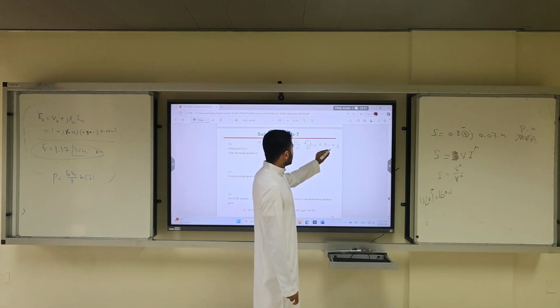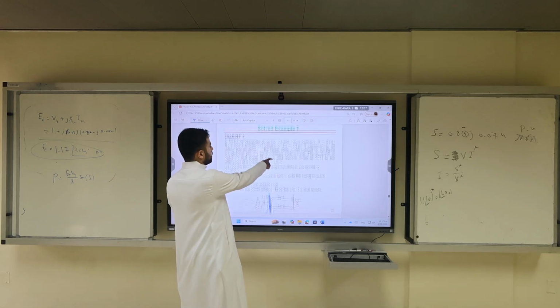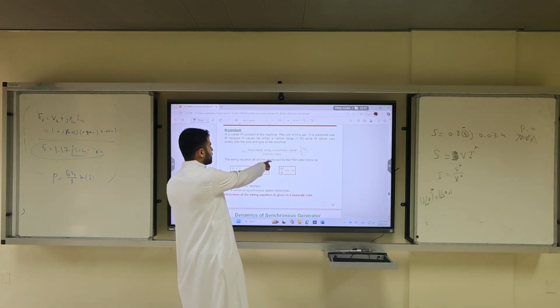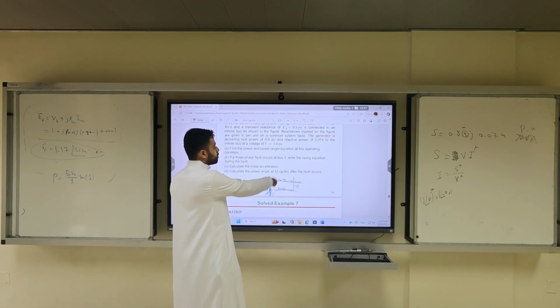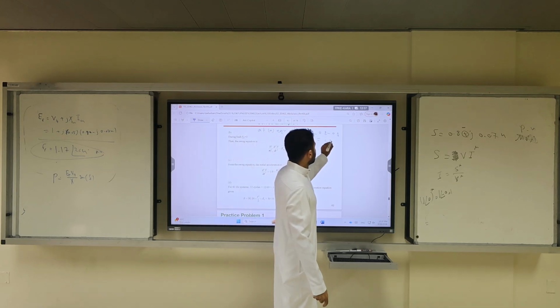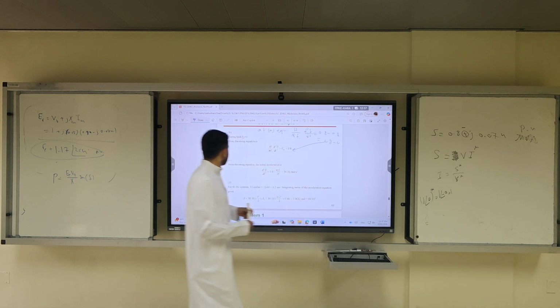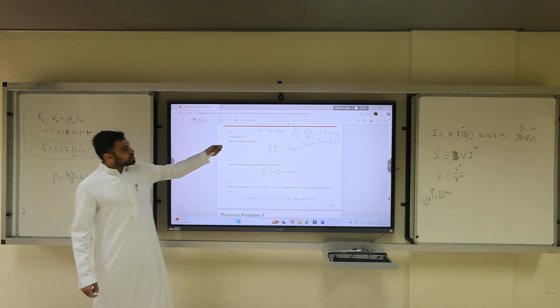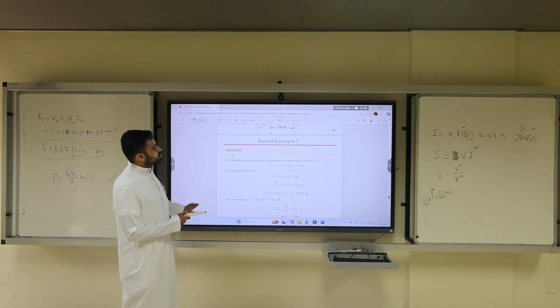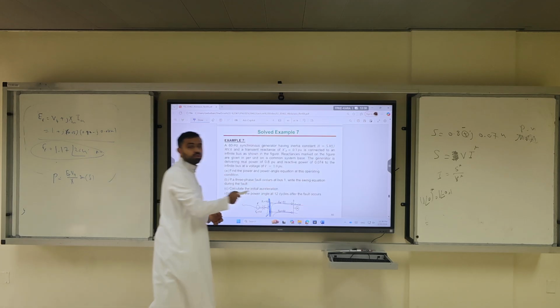But right now there is an electrical fault, so in the swing equation it will be 0.8 minus 0. So will it accelerate or decelerate? Accelerate, because it's positive. So at part B it will be acceleration. So this is the swing equation. So part B, what did he ask in part B? Write the swing equation during the fault.